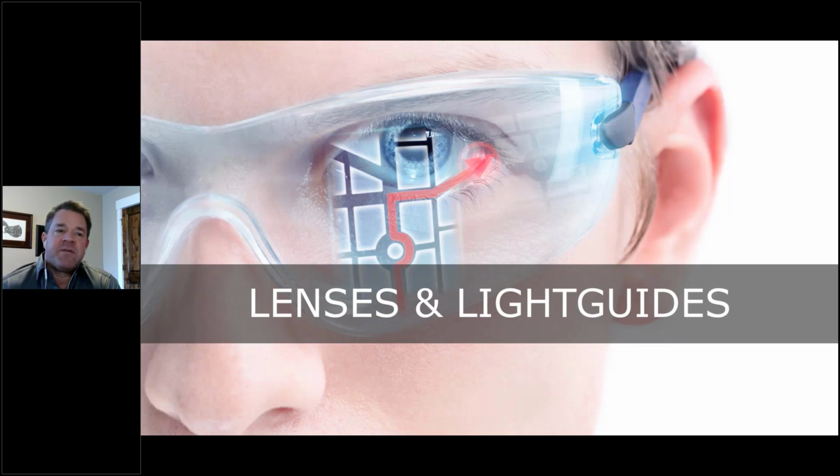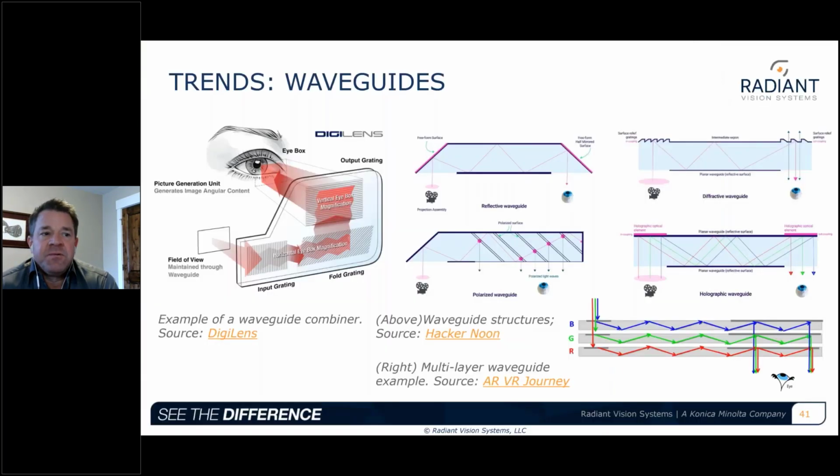Following the light's path from the display towards the eye, we reach the lenses and light guides. Waveguides enable see-through AR and MR device designs in a variety of compact form factors. The waveguide layer can have different geometrical structures, including reflective, polarized, diffractive, and holographic. The physical properties that help guide the light in these cases could be prisms, mirror arrays, or gratings, and even metasurfaces, all taking a range of unique forms.